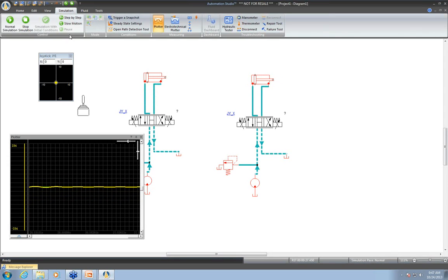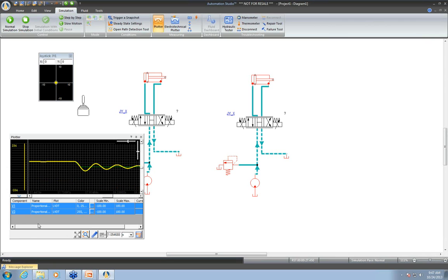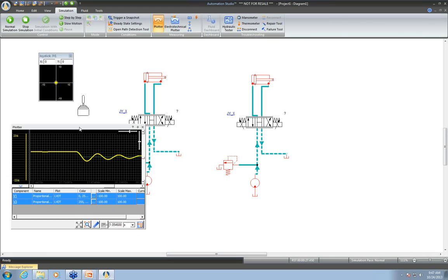If I pause the simulation here and go back a bit, previously what we used to do is the kinematic model, which you already had. With the new model, we are using the dynamic model, which takes into account the response time of this valve according to the flow and the settings on the valve. So you can see clearly here, the yellow one is the dynamic model and the green one is the kinematic model. Previously, we used to have an approximation in the plotter, which basically comes back unsteady, straightforward. Now with the improved model, we have more dynamic behavior of this valve.